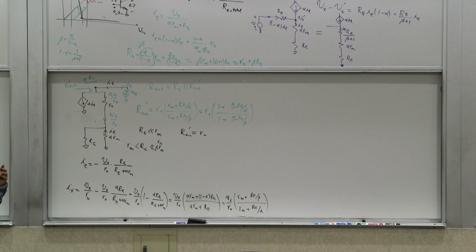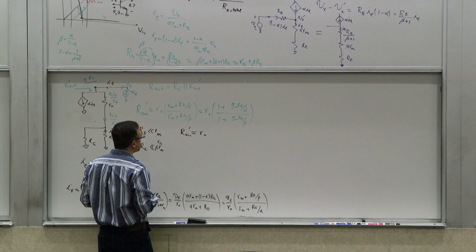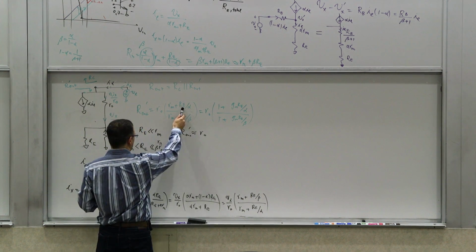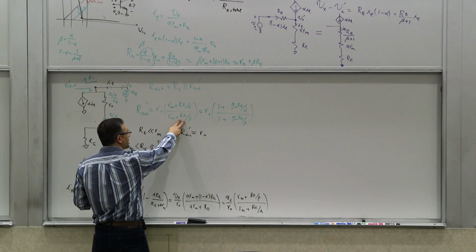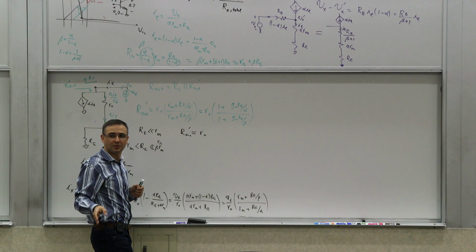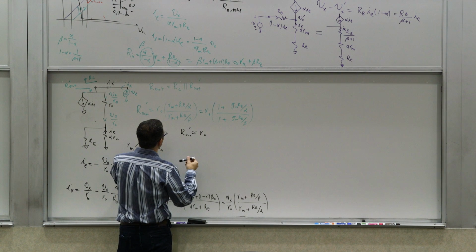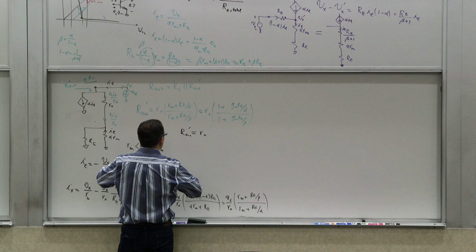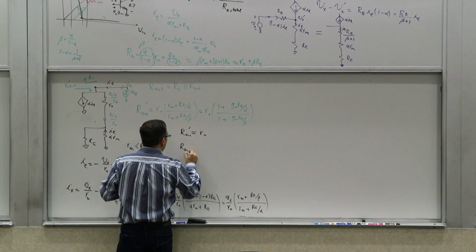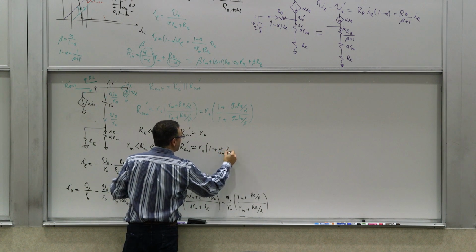So Re is between Rm and R pi, but it hasn't quite gotten to R pi yet. So what happens in those scenarios? Well, this term matters now, right? But this term still doesn't. So you get this divided by that, so basically it becomes Rm plus Re over Rm, which you can write as 1 plus Gm Re. This is something that you see commonly in a lot of situations, 1 plus Gm Re.